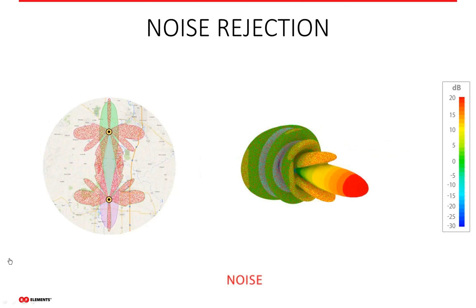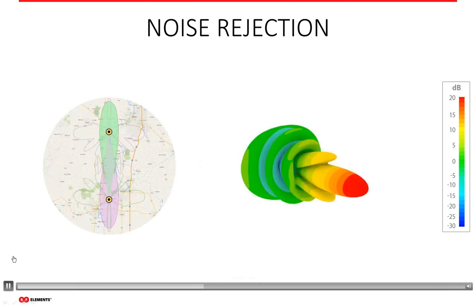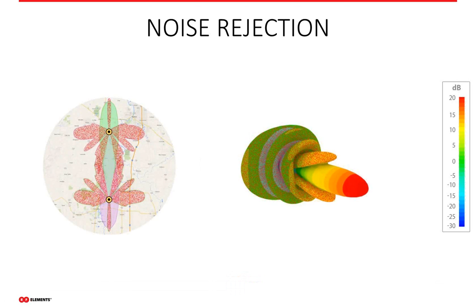Many companies actually create shielding kits, and some of the antenna manufacturers are creating these antennas with shielding or shrouds, as they're called, those kind of barrels that go around the outside perimeter. Those things are only really made to suppress those first two side lobes that shoot out at almost 90 degrees from the antenna itself. It does nothing to really suppress those other two lobes that come out above and below the main lobe. Those side lobes usually exit the shroud and therefore give you a much wider actual angle than you would expect. So again, noise rejection through parabolic dish antennas is actually quite low because of these side lobes.